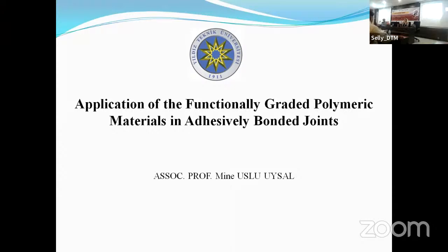Adhesively bonded joint technique is also hard for application, and especially for theoretical and numerical modeling, because adhesive does not behave like an orthotropic or linear isotropic material. It is different, so it is hard to model.